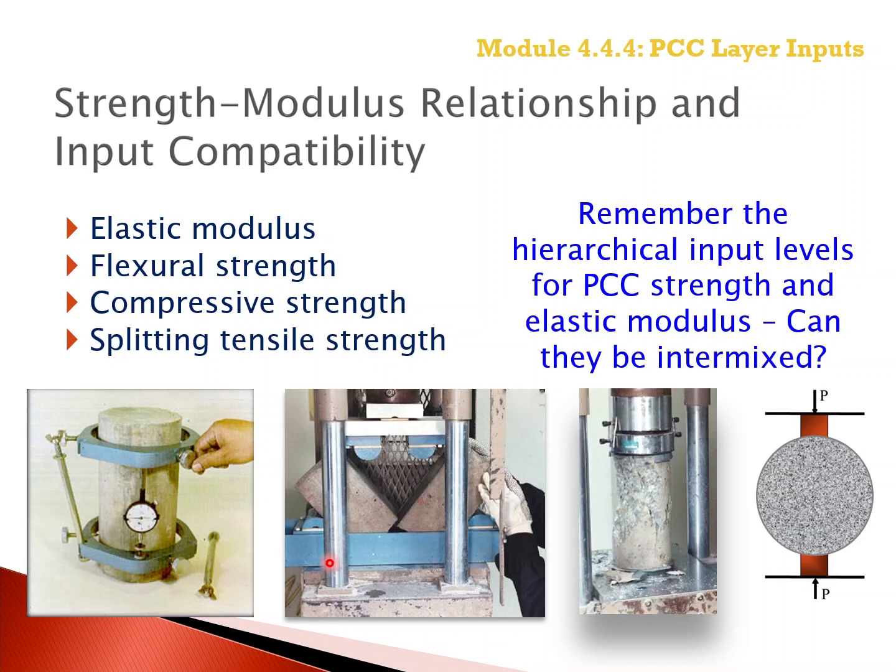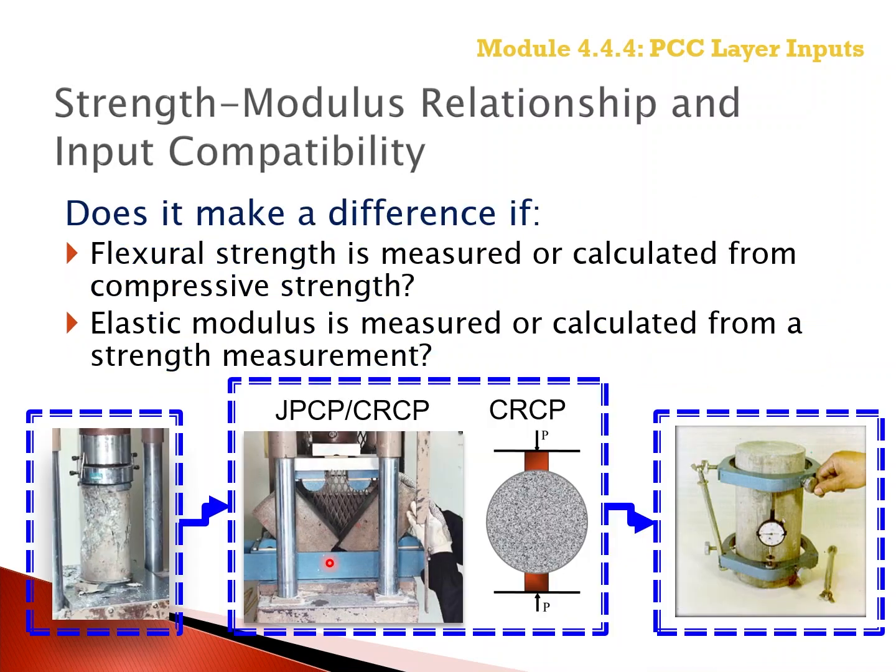Remember, hierarchical input levels for PCC strength and elastic modulus. Can they be intermixed? In other words, does it matter or make a difference if flexural strength is measured or calculated from the compressive strength? And does it make a difference if the elastic modulus is measured or calculated from a strength measurement?